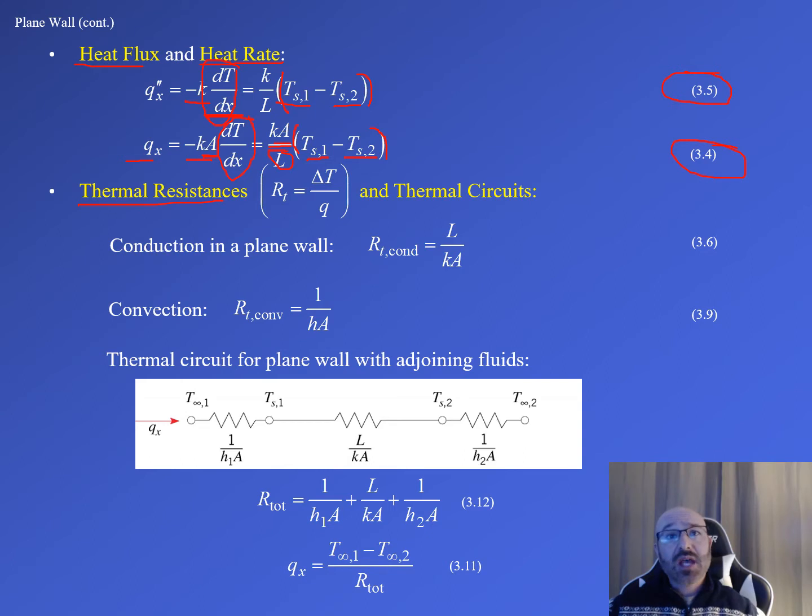So going forward with solving these problems, the next thing I want to discuss is thermal resistances and thermal circuits. Thermal circuits are going to be great, and it's really interesting how we can line these up with that initial diagram that we just saw in the previous slide to create these thermal circuits. But going back to thermal resistance, our thermal resistance, or R sub T, is in general form our delta T, our change in temperature, over our Q value. And again, we want to recall what our symbols are. What is our Q? Our Q is our heat transfer rate, so units of watts. That's another thing we really want to do as we're utilizing all these formulas and governing equations: pay attention to unit analysis.